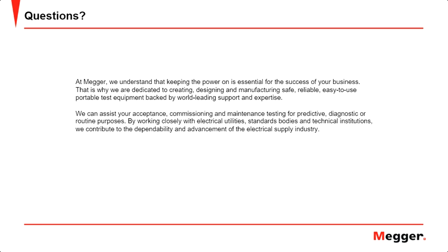Thanks, Josh. Chase, can you quickly go over the benefits and disadvantages of online versus offline PD testing? Sure. So during online testing, the benefit is that you can actively see that you have partial discharge on a live gear or cable that you're testing. The disadvantage is that you're not going to be able to see what type and how bad the extent of your partial discharge currently is.